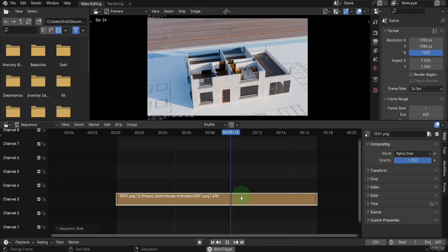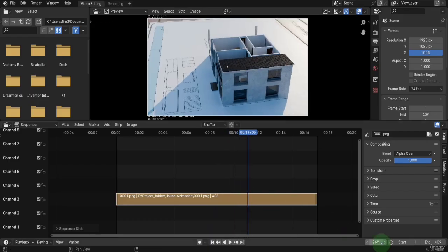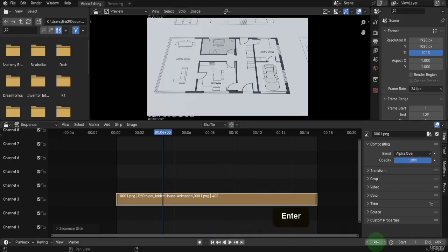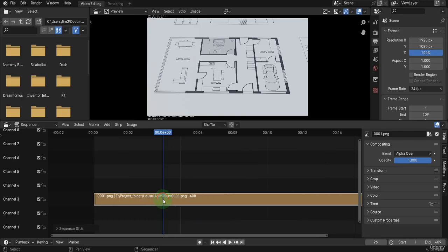So for example, if you see an issue with one of the frames here, frame 96 for example, the scrubber or playhead displays the image to the right side. So if you wanted to remove the image on screen, select the strip, press K to make a cut. Press the right arrow key to step forward one frame. Press K to make another cut.